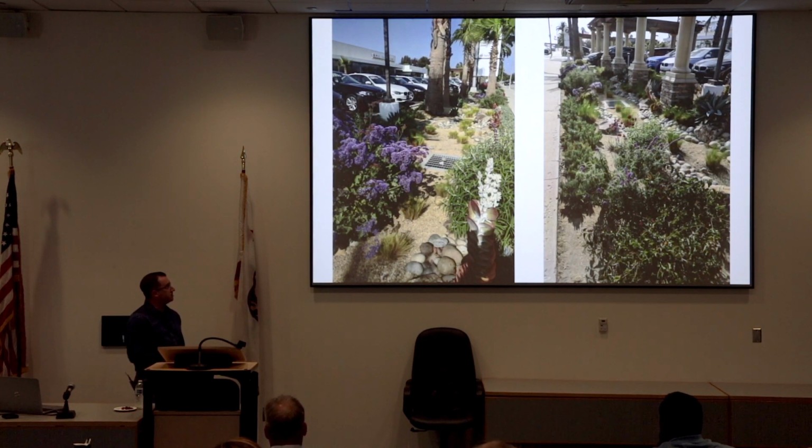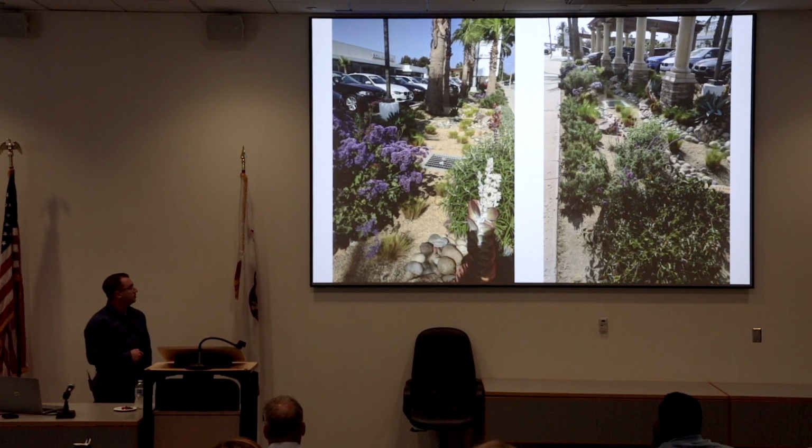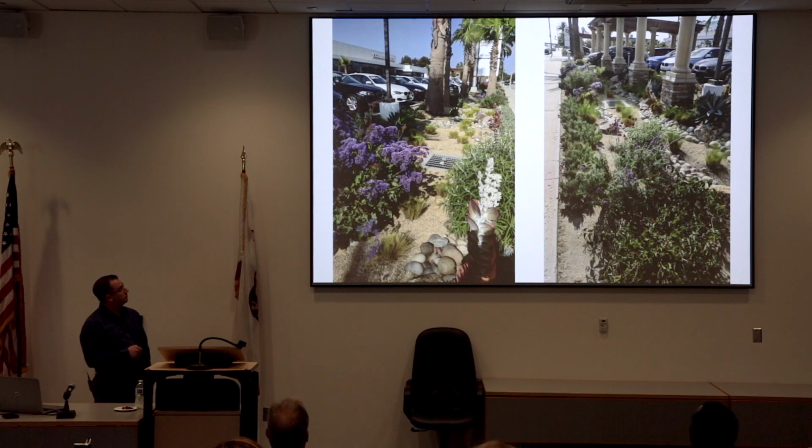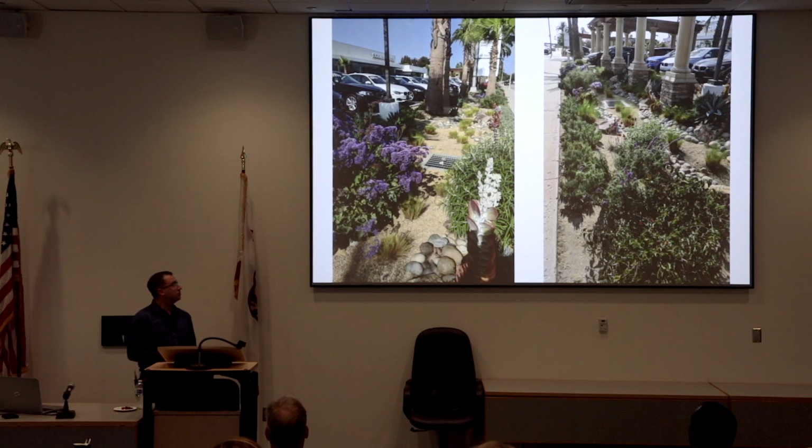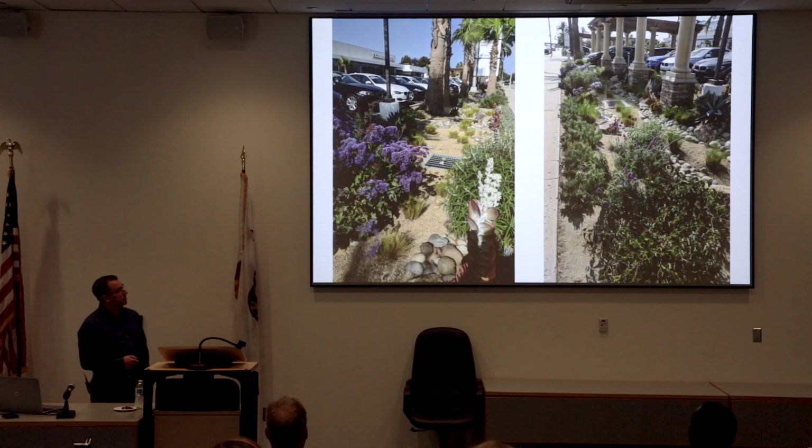The main difference is that you actually have a drain inlet. And so as the water runs off from the parking lot through the curb openings down into here, it's going to run through the rock, it's going to run through the low points, through this grass, and eventually it'll make its way into the drain inlet. So they look very, very similar, but they're actually functioning very differently.